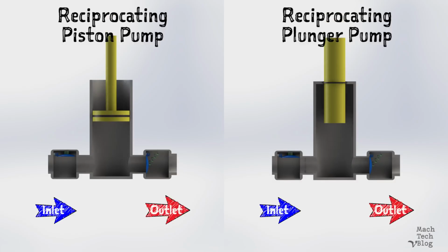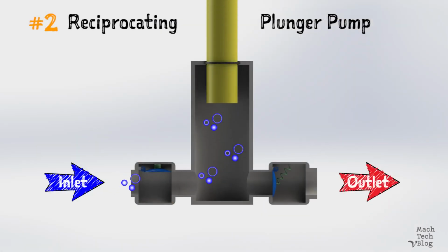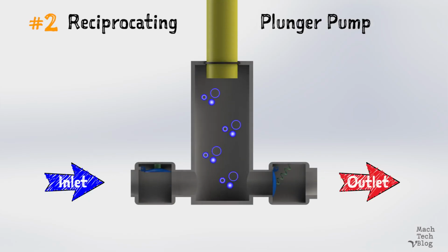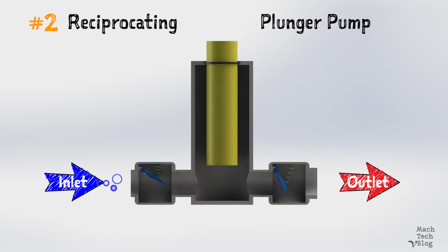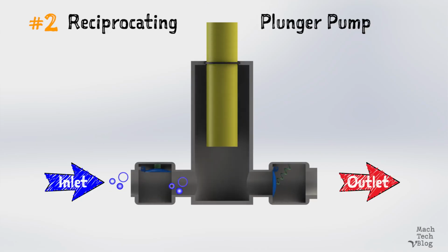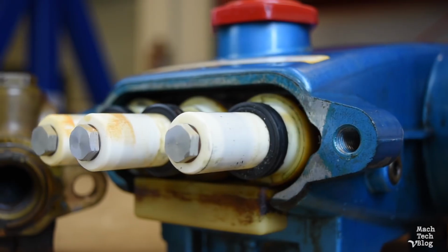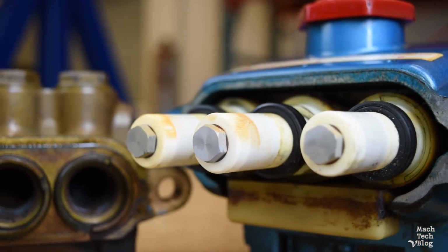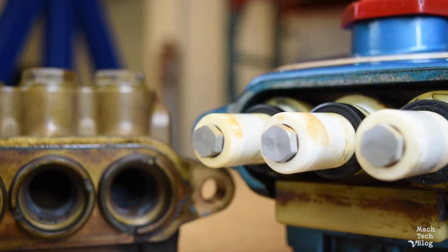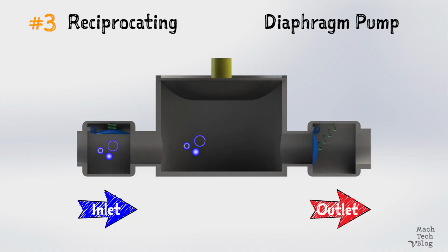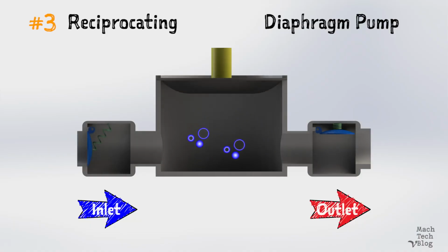Unlike a tight-fitting piston, a plunger fits loosely in its cylinder. Just like when your bathtub overflows because you filled it too full with water before jumping in, the physical mass of the plunger alters the size of the chamber and displaces the fluid. This is a triplex plunger pump, which uses 3 staggered plungers for smoother flow delivery, but it is otherwise the same as our demonstration.